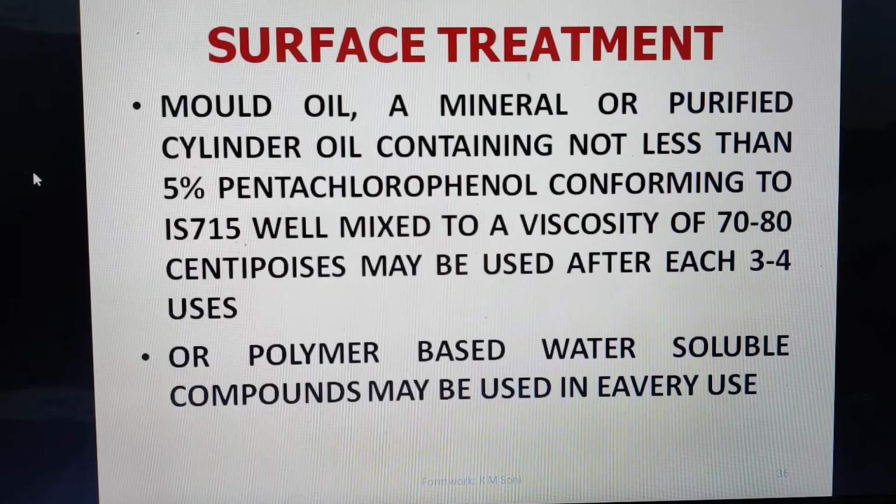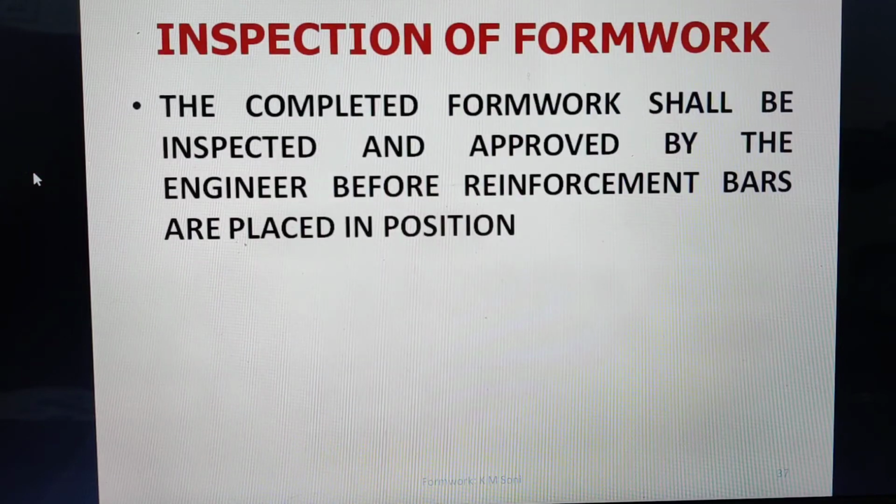And then surface treatment is to be given in case of shuttering or formwork. So shuttering oils are available. Nowadays even polymer based water soluble compounds are available. So they should be used.